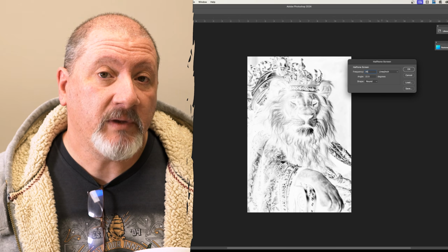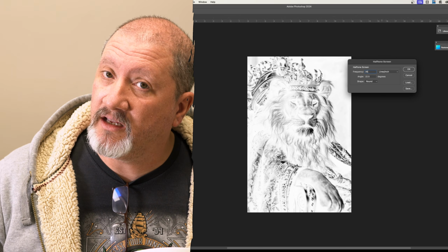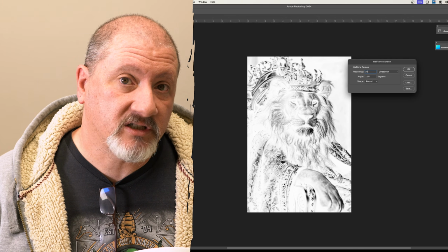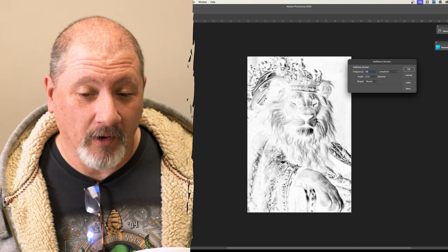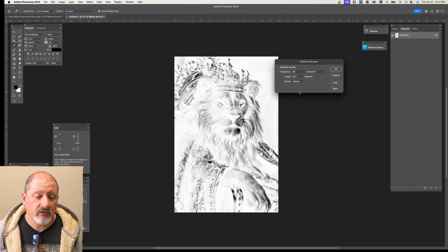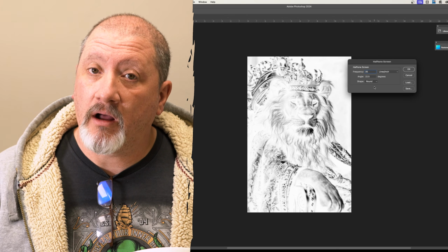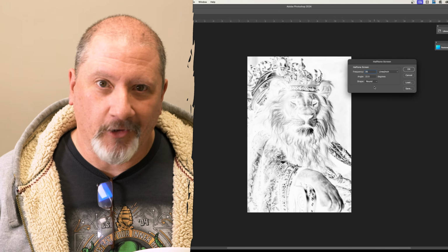So eliminating that color being printed means that we can do different things with our dot halftone size, how small or fine our detail is, because we don't have to worry about the registration of the white. We're printing light. So I'm going to do this one at 35, then I'll do another one at 45, and then a final one at 55. And I'll print all of those out. I'll transfer them to a shirt, and we'll see how they all look.